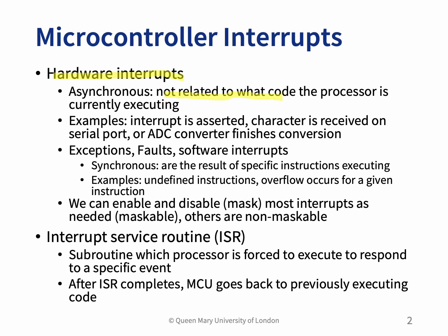So when an instruction is being executed within the processor, it is not related to the interrupt inside the processor, where this hardware interrupt is responded or interrupted by the external device. For example, when an interrupt is asserted, a character is received on the serial port, or when the ADC converter finishes the conversion.